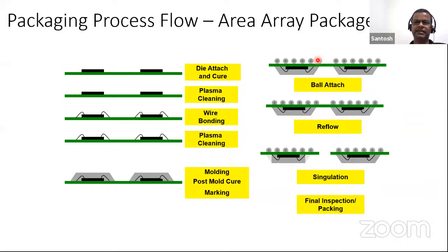After this, these balls go for reflow. Reflow means that these balls get attached to the substrate pad area. After this there is singulation, and this unit becomes an individual unit that goes for the final package.